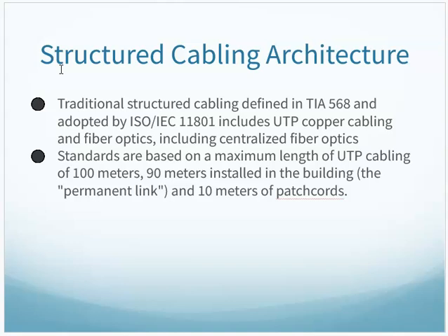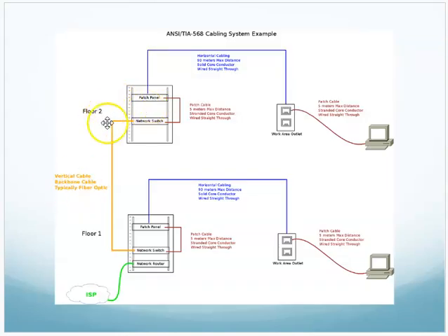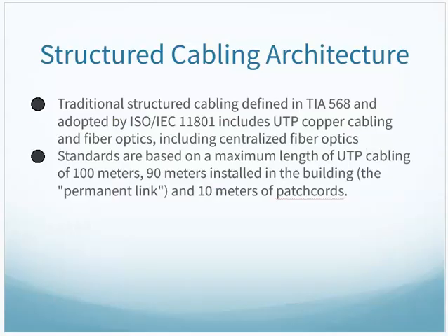It also allows fiber optic. And as we said before, that's typically for, let me show you this picture again, connecting my closets together. These could be separated by a floor, or these could be literally in two entirely different wings of a building that I need a long fiber link to connect them. So the fiber optics is typically used for bandwidth as well as distance needs.